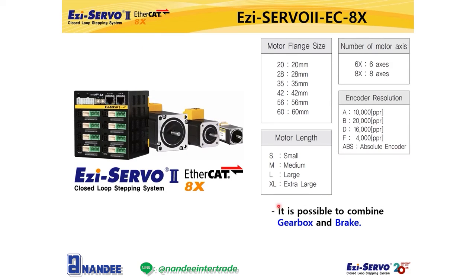Gearbox and brake specifications are also available. A gearbox and a brake can be applied from a NEMA 17, 42mm size motor, to a NEMA 24, 60mm size motor. Gearboxes are planetary gearboxes. The brake is a non-excitation type that activates when the power goes off. For example, you can use it to prevent the Z-axis load from falling. Please refer to the catalog for details.